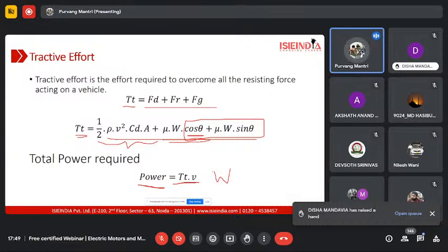They provide conversion kits, and in those cases, they use the stock transmission of the vehicle. For example, the Swift Dzire has a 5-speed gearbox, and they did not take out the transmission; instead, they directly mounted the motor to the transmission case. In that case as well, the motor functioned pretty well with the gears of the vehicle.